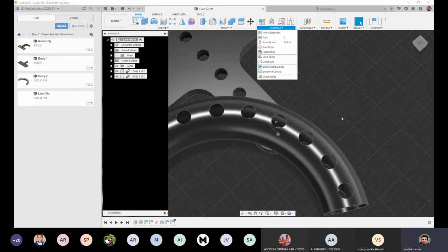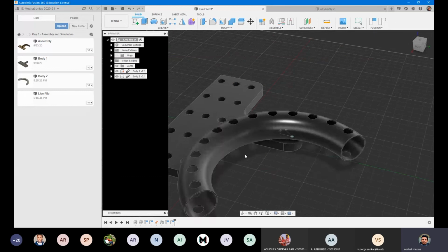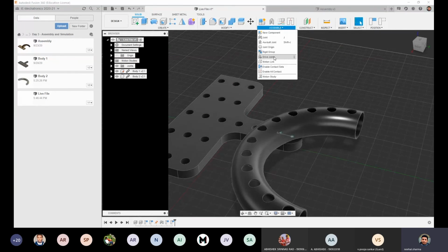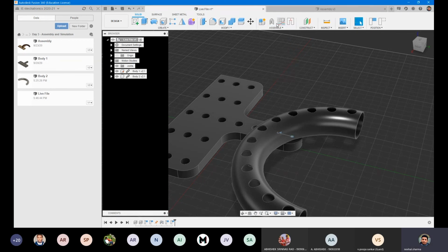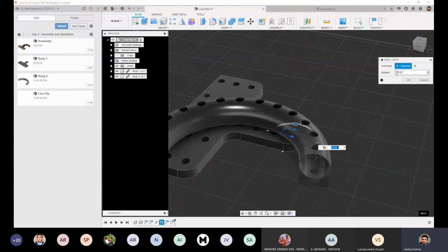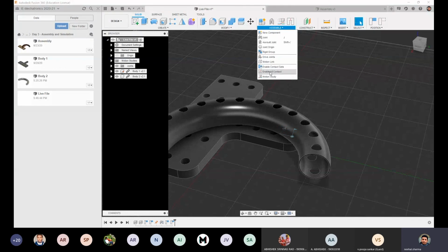And as for drive joints, in this case, what I was doing was explicitly moving this part around the joint. But in case you want to give a speed, or not just speed, in case you want to define a specific angle to this joint that you're making, you can use the drive joint feature and also do this. You can explicitly set an angle like that. And yes, the most important one is this contact set option.